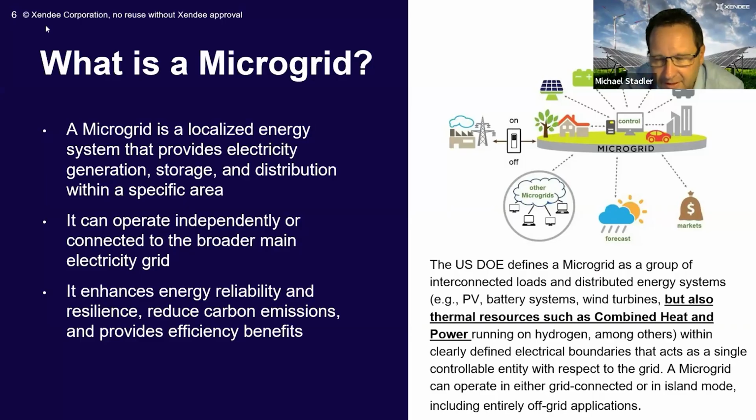And on top of this, and this is how microgrids actually started 20 years ago, it was with combined heat and power units, because with CHP systems, you can use the waste heat for building heating, but also for cooling. And that's actually now a renewed interest for data centers that we are seeing, because with absorption chillers combined with cogeneration and or co-location of generation resources, we can reduce the electricity demand, because we're taking out electric cooling and use the waste heat for this. And that's what we're seeing in the work that we're doing with data centers. So it's really about the system efficiency increase.